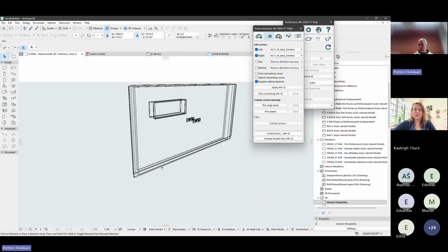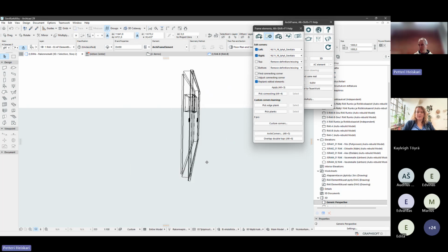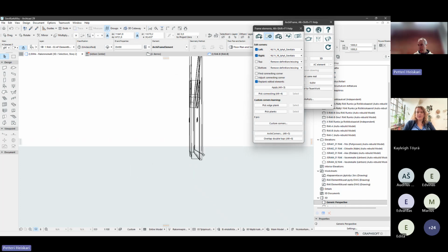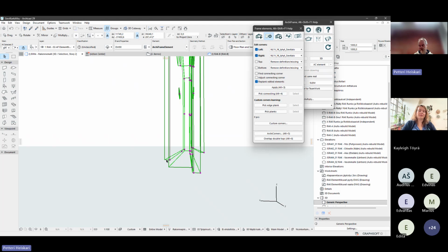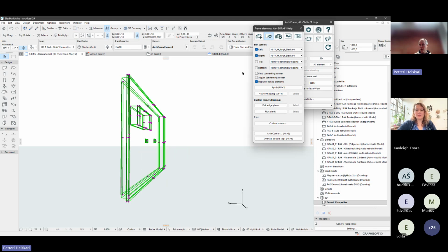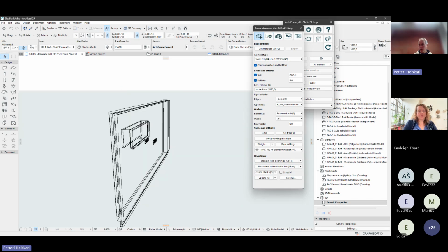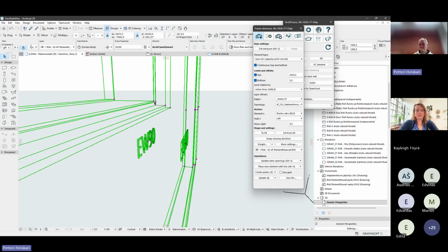Then what we have in 3D, we have the placeholders, and here you see what the layer offset means. So here the inner layer starts higher than the main framing, and the cladding here also starts higher. So you can control all these edge offsets, and then also for this opening, to be able to install the metal plate taking the raindrops away, it's slightly going downwards with the layer offset.